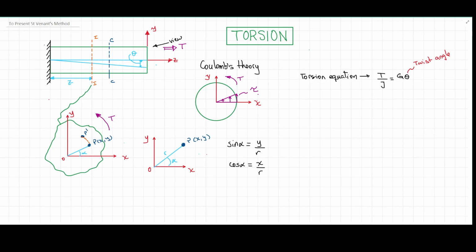as you move to the end of this piece. Now, because of this non-symmetrical condition, torsion is not only going to create a twist, which is going to induce shear stresses, but it is also going to induce or cause warping. So the phenomena happening here are twist plus warping.